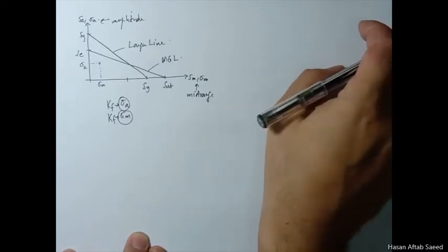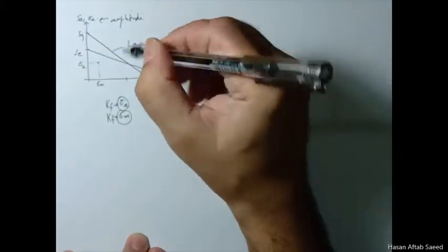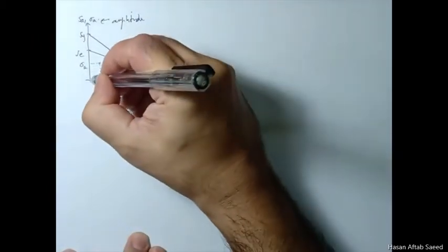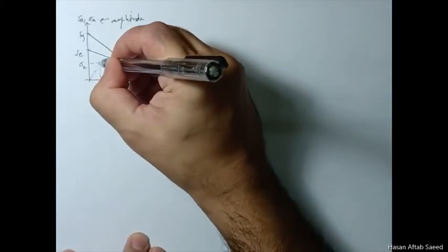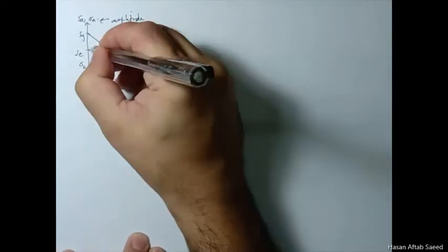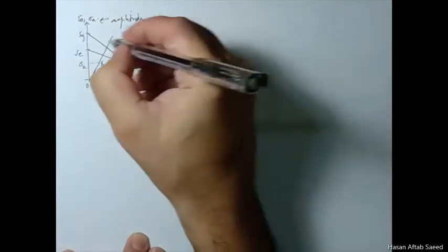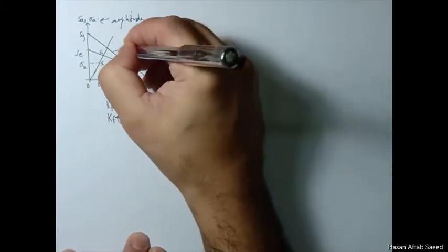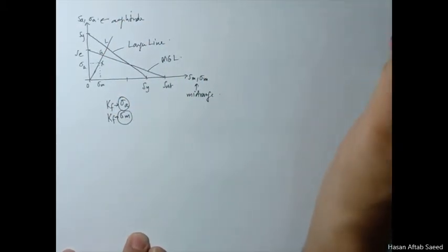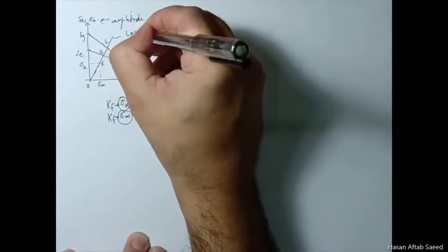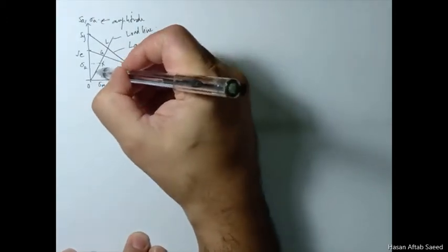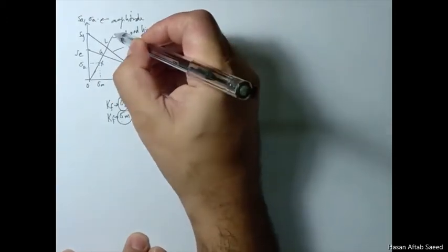But actually what we do in reality is, instead of plotting it like this, we draw from the origin, joining this point and then extending it. This is the origin, this is your point x, and where it intersects your Modified Goodman line, let's call it the point G, and where it intersects your Langer line, let's call this L. So if we were to do it graphically, this is the load line. It is nothing but an extension of OX from origin to this point and then extending it.